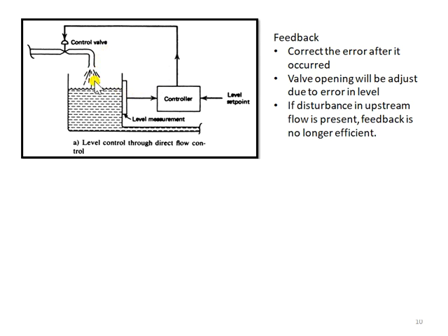However, this is by assumption. This control is fine by the assumption if the flow rate to the input is well regulated and stable. So the problem will be significant, or the performance of the controller will drop, if the input flow rate is not regulated or is not stable.